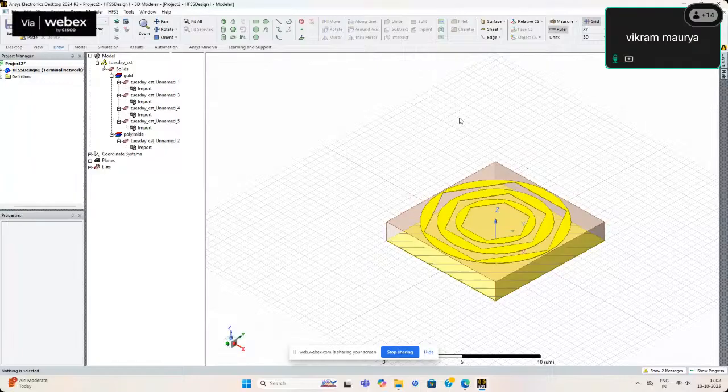Okay, that is a little bit challenging part for assigning the boundary condition and the Floquet port, that we will cover in the next session tomorrow, so that we can directly make a boundary box and we can directly simulate those structure, and we can check all the parametric results, whether the similar result will come or not, and how much the port distance we have to assign.